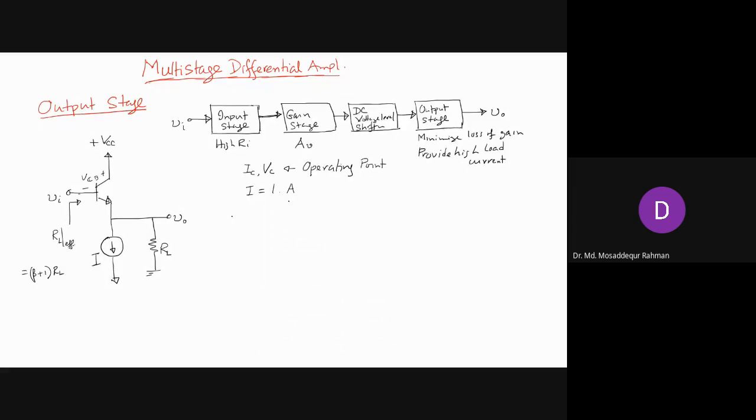So you take 1 ampere current. This is a large current, and that will obviously satisfy your requirement. This is your, let's say, load current I naught, the signal current. The condition is that your bias current should be greater than or at least equal to I naught, right? If the bias current is greater than or at least equal to I naught, then it will be able to support this load current for all range of its values.